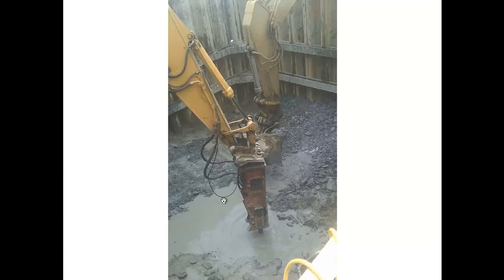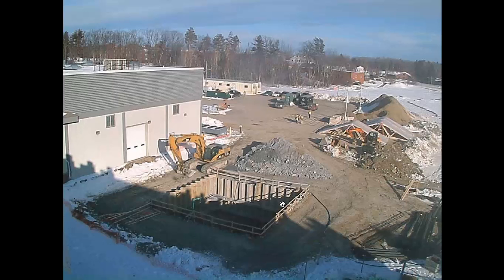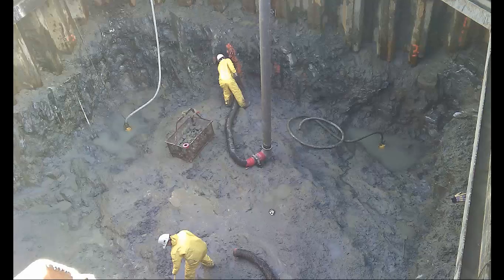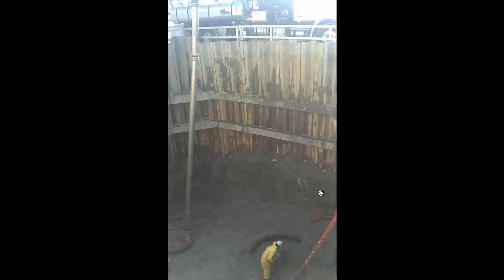Down here we've got a close-up shot of them drilling with these hydraulic rams into the bedrock and excavating the excess material out of the bottom. So this is about 30 feet down in the ground right now. You can see the water pump, it's pumping the water out. They're actually cutting into the stone down here, and they're going to drill that and put some anchors in to actually pin the foundation right to that bedrock. Just another picture of them dewatering.